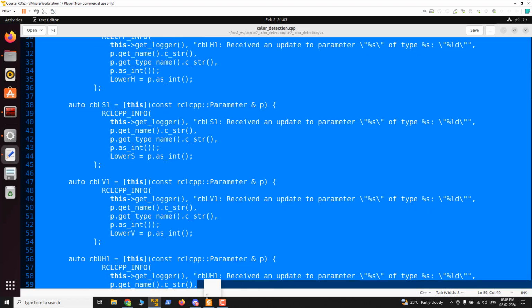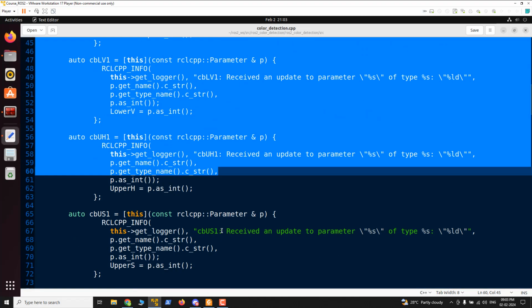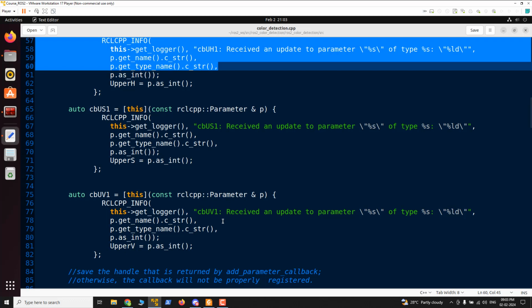Dynamic parameters in ROS 1 are basically for changing parameters. In ROS 1, we can set the parameter and change it, but the node will not be updating. For example, you have set a parameter, and then you ran a node, then you change the parameter, but the node doesn't know the value has changed unless it is constantly reading that parameter.